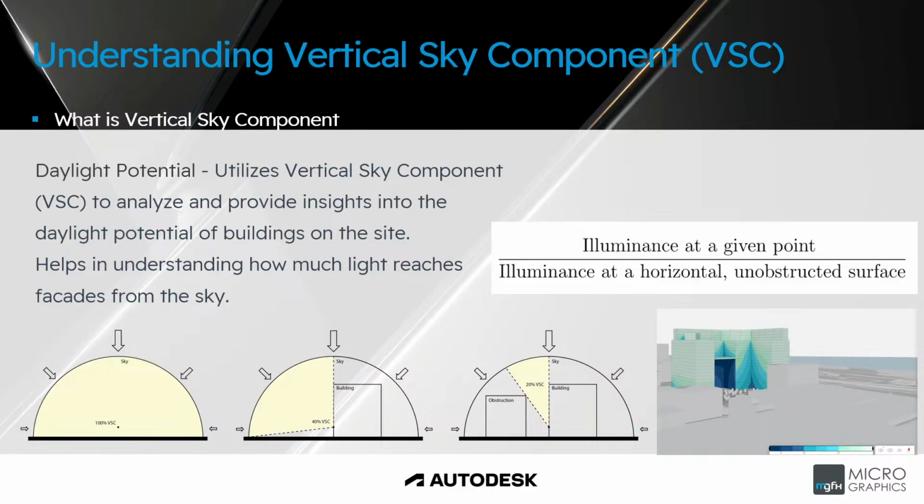Sky component is expressed as a percentage. The illuminance on a horizontal surface, for example an empty space, without obstruction is defined as 100%, whereas the illuminance on a vertical surface, for example a facade or a wall, without obstructions is almost 40%. The reason this is not 50% is due to the sky model used, the CIE overcast sky, where the sky at the zenith is 3 times brighter than at the horizon.